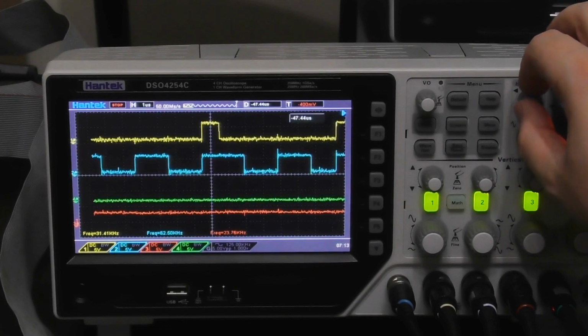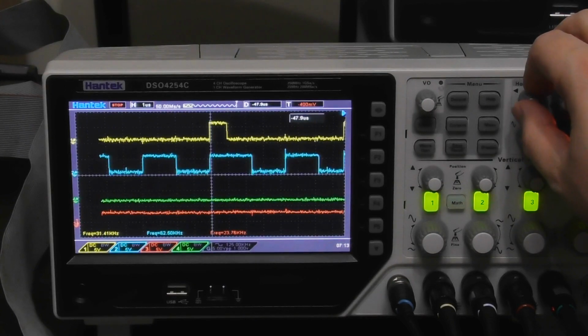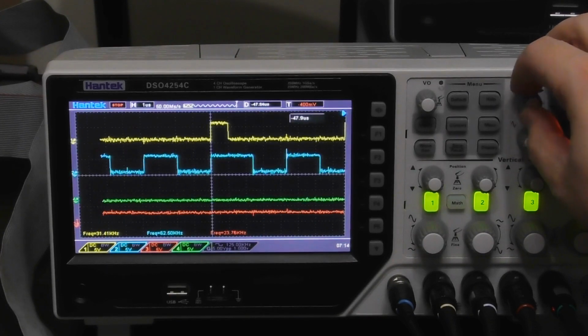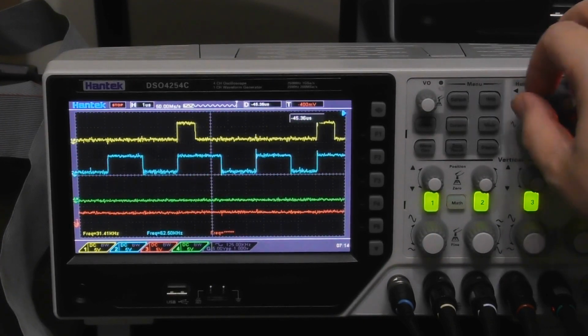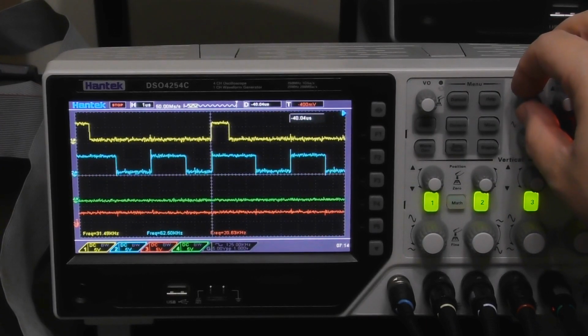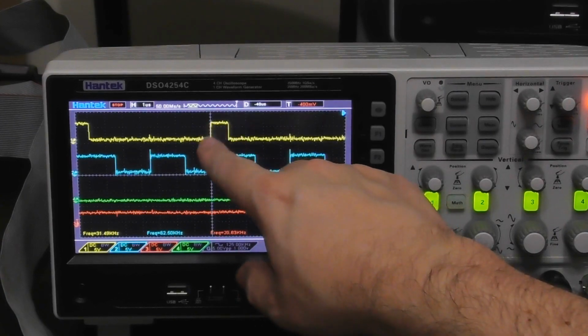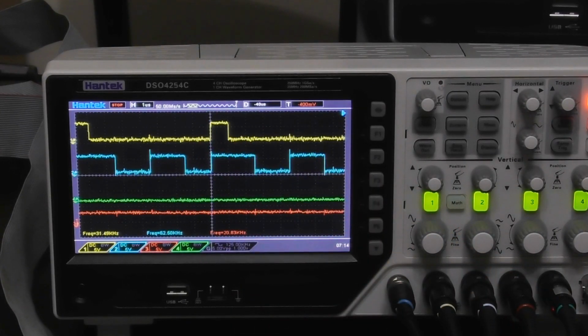Okay, so that's the first pulse. Actually, my clock is rising really early there. I think that's just about missing the edge of that pulse. Interesting. And over here it got a 0, and again here. I think the reason that this triggered my capture was that this clock pulse in blue here was too early compared to the actual data from the disk.